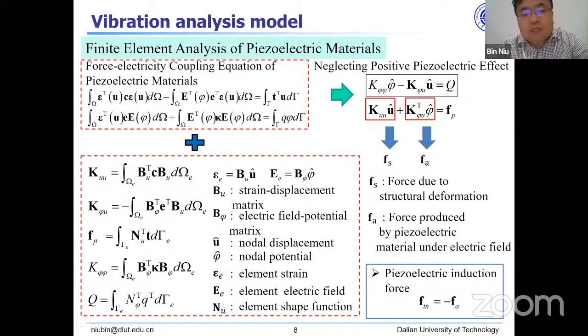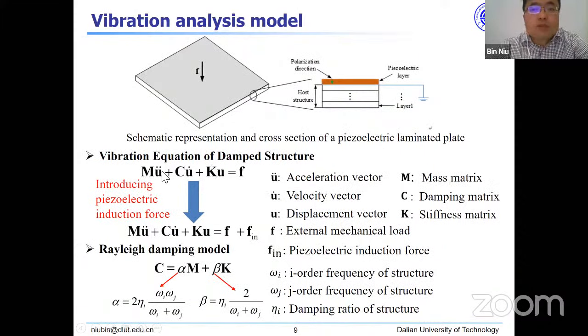So we consider the piezoelectric material as some kind of actuator, so we can get this piezoelectric induction force. For vibrations, from the standard vibration equation, we can just introduce this piezoelectric induction force here. Then we get new equations. Of course, when you apply these piezoelectric patches, you will introduce some mass, damping or stiffness contribution to the equations. And sometimes we use the standard Rayleigh damping model. So now we have these equations for the analysis.